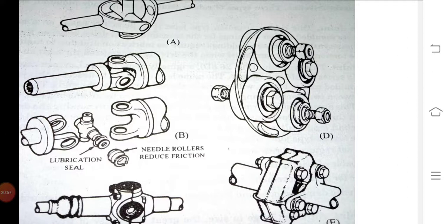It uses a number of molded rubber blocks with specially shaped cavities at the end side, and these blocks are sandwiched between two steel pressings, and each shaft is connected by means of a fork to alternate for transmission through a small angle. The blocks also accommodate a small axial and angular movement for shaft length alteration and torsional damping, and this coupling is relatively large in diameter.